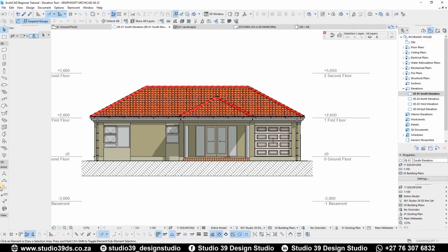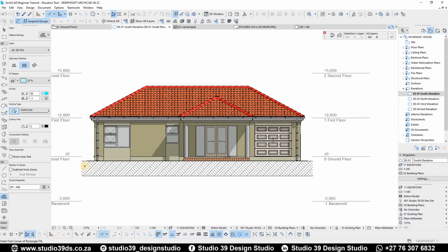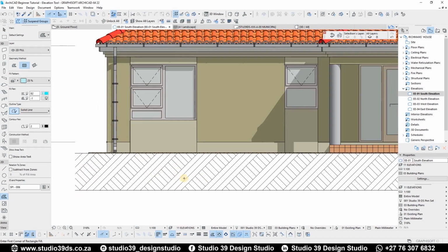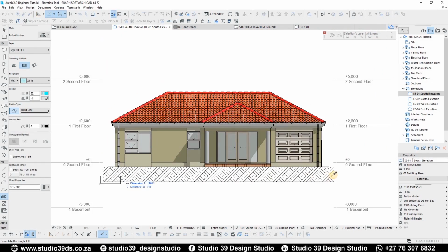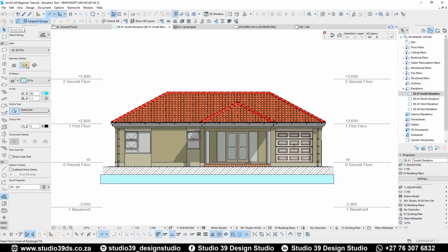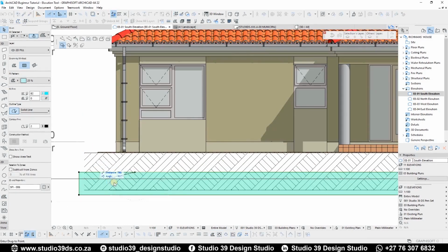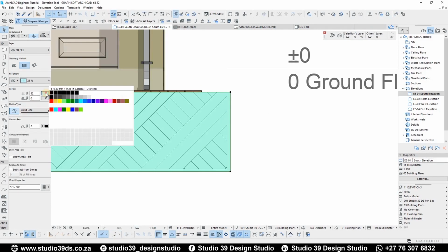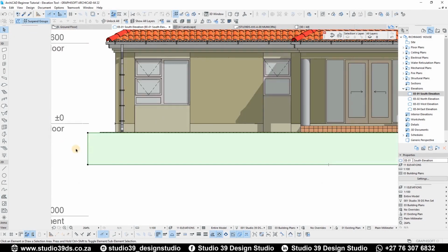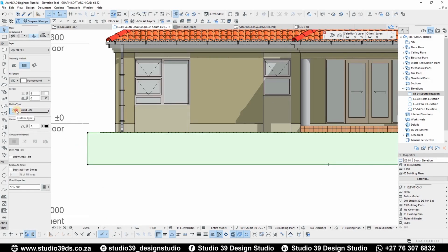So with that said guys, other things that I usually do when I'm doing my annotations on the elevations: I don't want to show the cut fill of this specific mesh tool, so I can always just do something like this. Let's make it about 25, and the other one is going to be like that, so that I can see through it. And that's what I come up with. So I'm going to take this fill and switch off the outer line type.